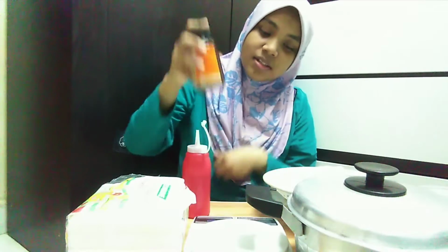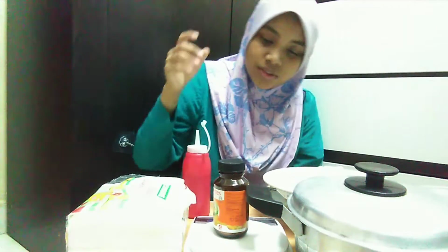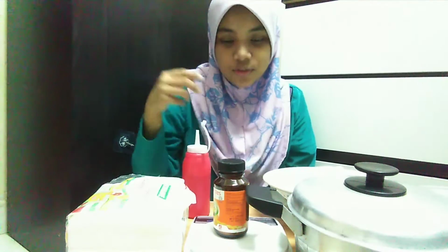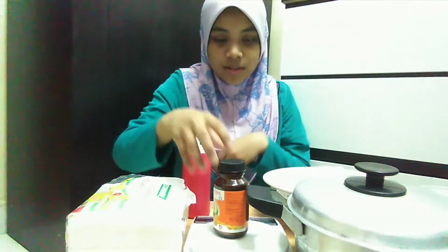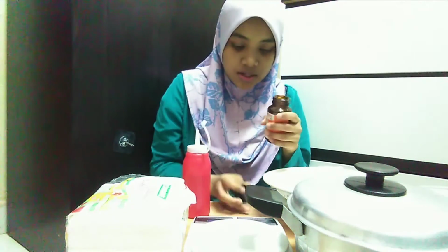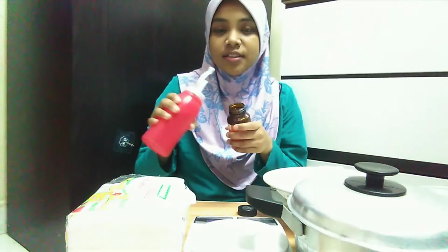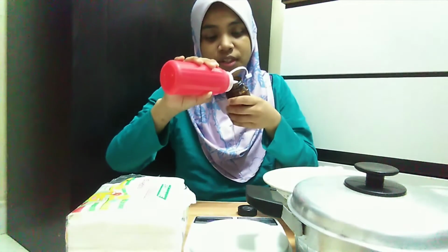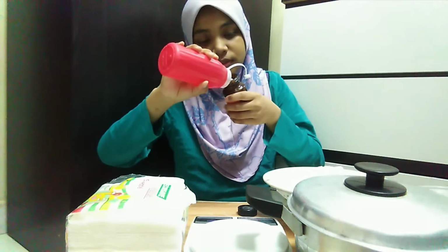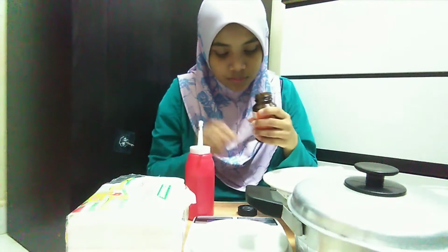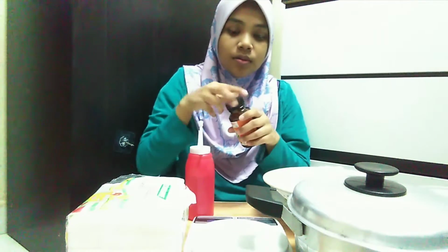And we take the mass of soil sample, density bottle and stopper. After that, we use 10 ml distilled water and put it inside the density bottle. We shake and leave it around 2 to 10 hours.